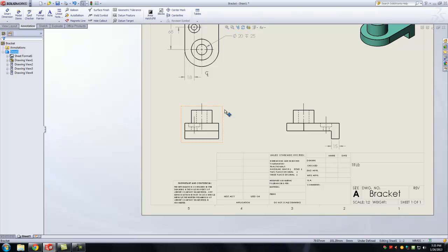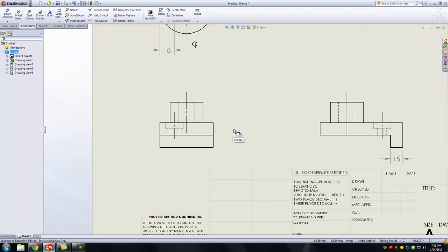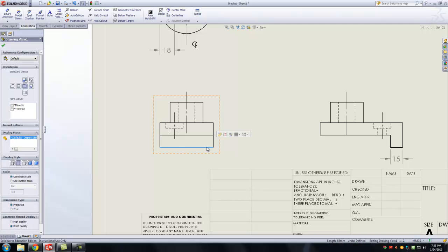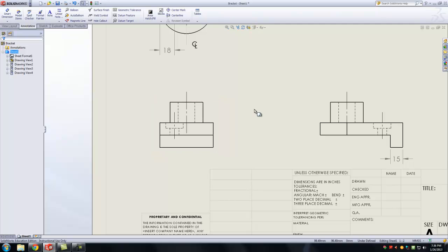Okay, so look at this. We're going to use a different way of dimensioning. So remember we talked about datum. Now I don't expect you to select datums for your homework because you don't really know what those parts are used for. So that's why we just pick a line, and usually I pick the base and just measure everything from that base. Now another way of dimensioning is instead of selecting Smart Dimension, if I click on the drop-down menu, there's an option called Vertical Ordinate Dimensions. So the reason you use this is it just creates a cleaner dimensioning scheme.